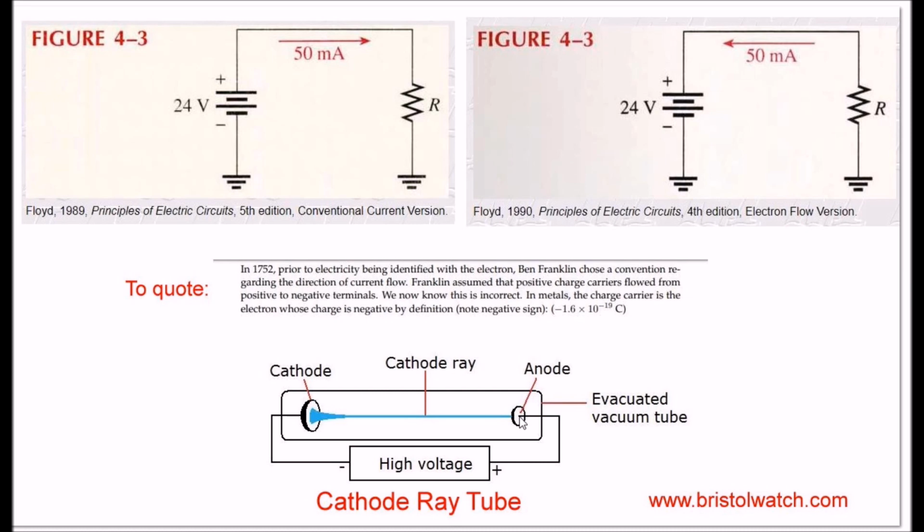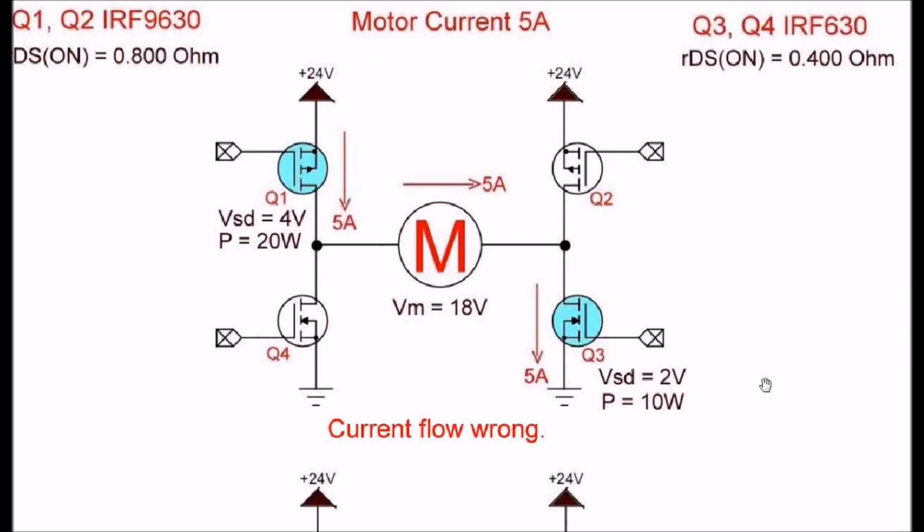All right, let's ask a question here, and let's look at something else. One of the explanations I have for diodes and bipolar transistors is that the arrow points in the direction of current flow. Well, not really. The arrows actually point to the N-type material. Take a look at these MOSFETs. The only current flow you're going to have is from source to drain and drain to source.